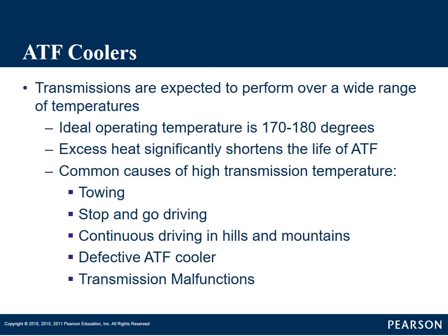If you have a defective automatic transmission cooler, whether it's a restriction or air's not getting through that cooler, maybe the engine's overheating, engine's running a little hotter, which makes the transmission run hotter, and we'll talk about how that is here in a second. Or just transmission malfunctions. Maybe your torque converter's slipping more than it's supposed to be slipping, and that can create excessive heat within the transmission.